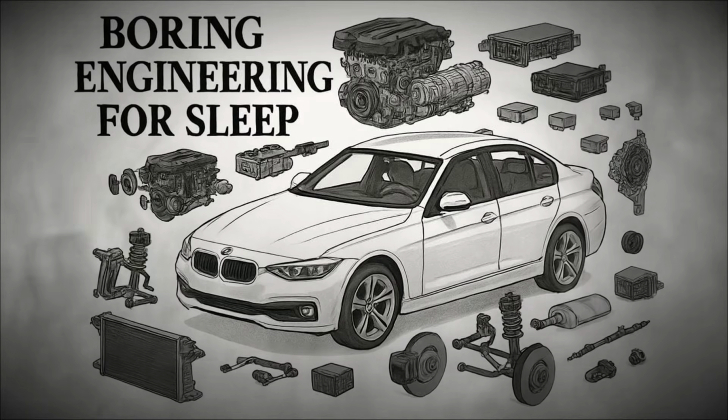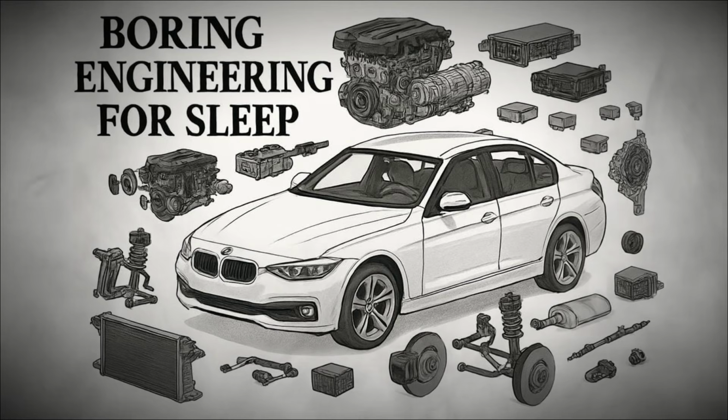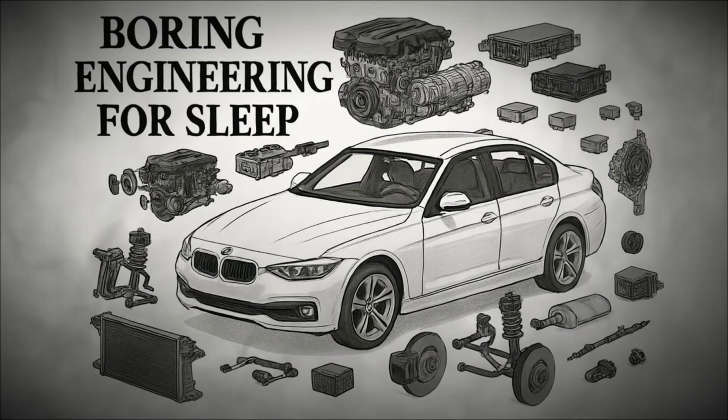In a manual transmission car, the clutch pedal on the floor is directly linked to the clutch mechanism, and pressing the pedal disengages the clutch, while releasing it re-engages the connection. The main parts of a typical clutch system include the flywheel, the clutch disc, the pressure plate, the release bearing, and the actuating mechanism. The flywheel is a heavy rotating plate attached to the crankshaft of the engine, and it provides a smooth surface for the clutch disc to press against.